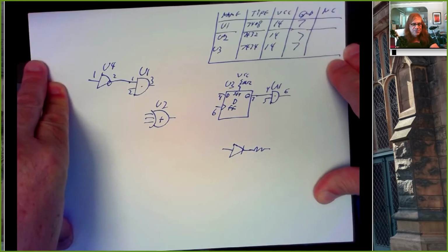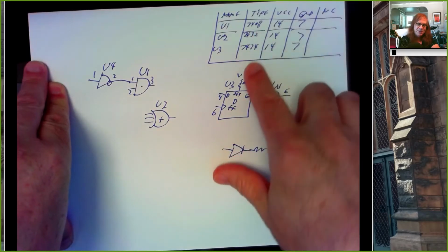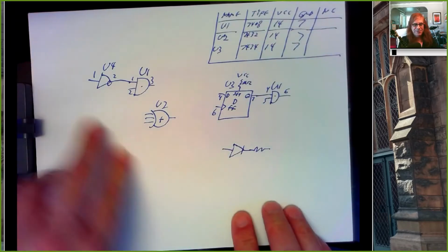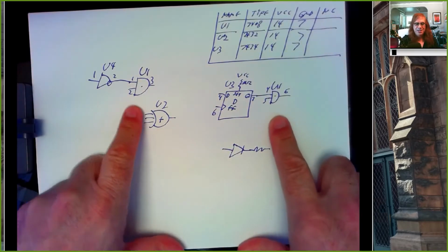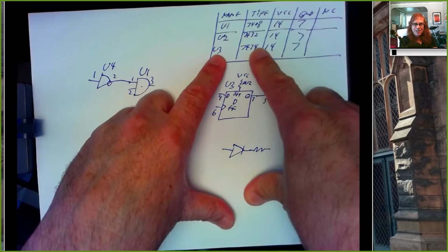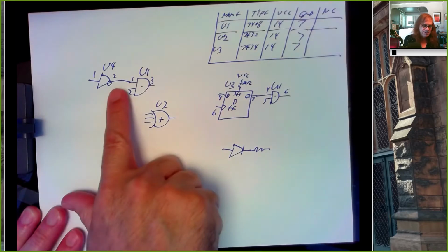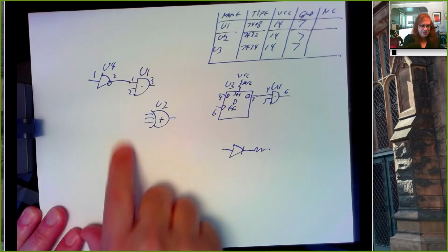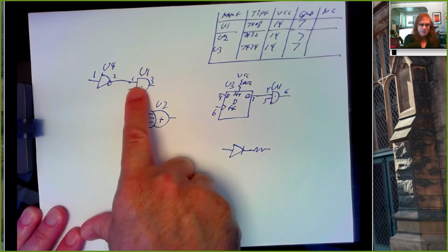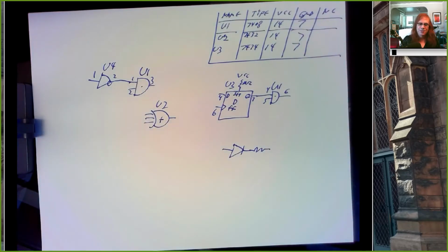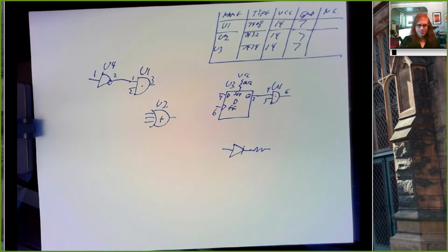And now you just get a proto board, you grab one of each chip that you have in your component ID block. If you've got 2 separate AND gates, you'll have 2 entries up here for an AND gate. So you grab 2 AND gates, right? And you put these into your proto board and you just start making wired connections. Wire from pin 2 of this chip to pin 1 of that chip, plunk in your wire, that part of your circuit's done.